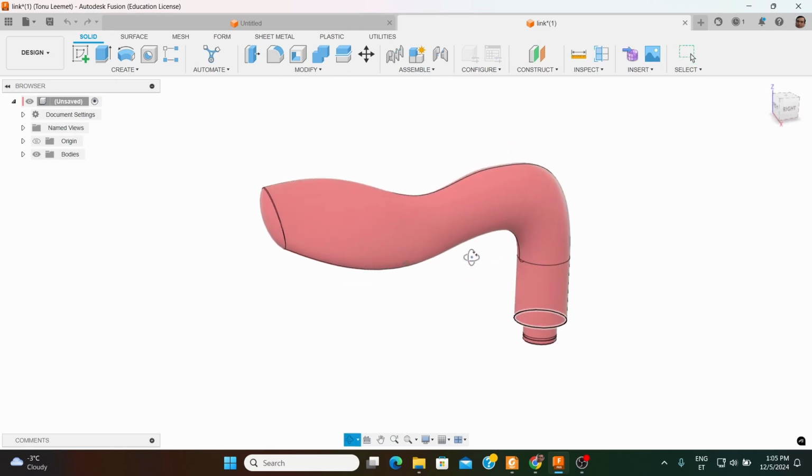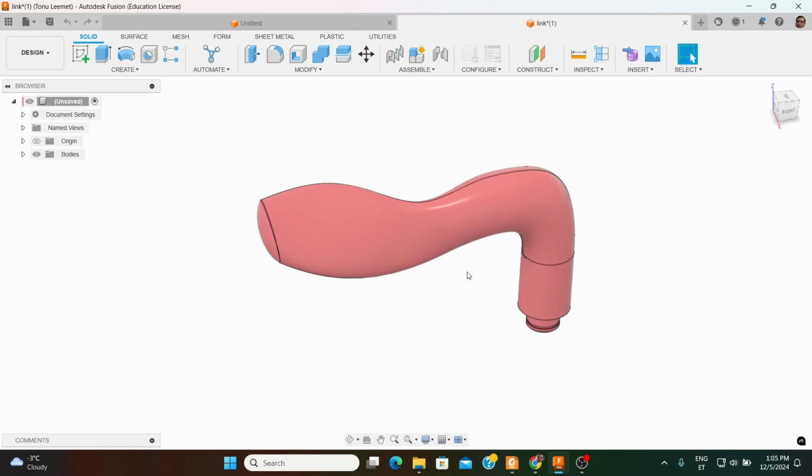An important thing to mention in Fusion is that when you bring in a CAD model in neutral format, as it was a STEP in this instance, Fusion starts in what is called a direct editing mode, meaning that you have access to some different tools, but most importantly, you see there is no timeline.